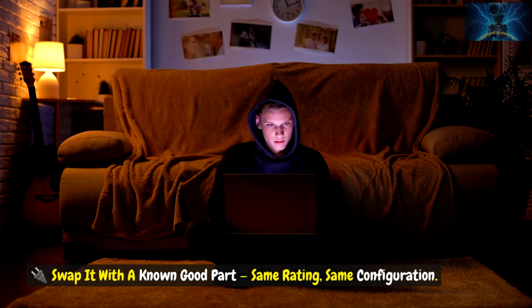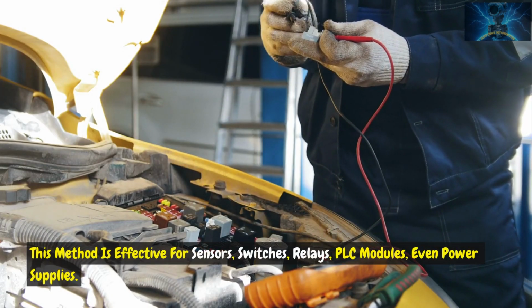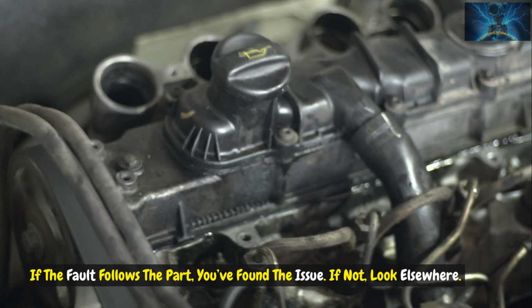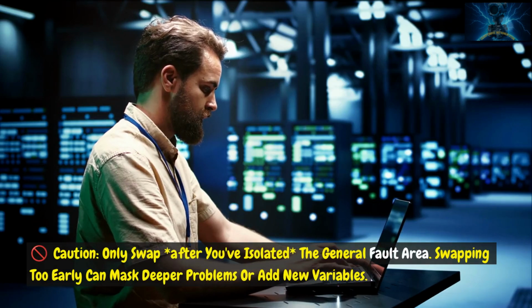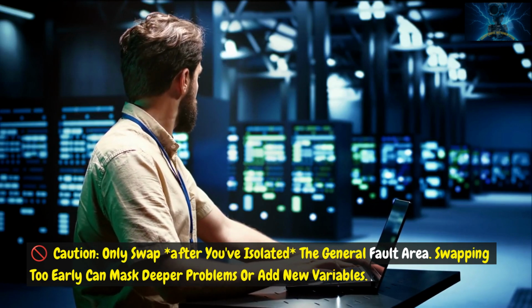Component swap. Not every failure is obvious. Sometimes components fail subtly or intermittently. Swap it with a known good part. Same rating, same configuration. This method is effective for sensors, switches, relays, PLC modules, even power supplies. If the fault follows the part, you've found the issue. If not, look elsewhere. Caution: only swap after you've isolated the general fault area. Swapping too early can mask deeper problems or add new variables.